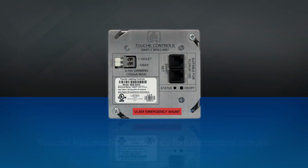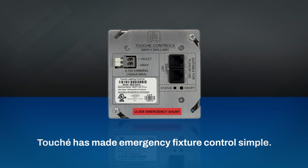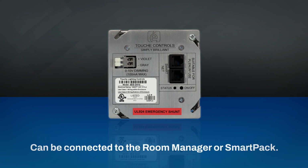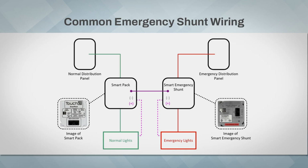As Touche does with everything, we came up with a simpler way to control emergency fixtures. We designed our own UL 924 listed smart emergency shunt modules. There are 2 different variations, one that has dimming and one that is switching only. The smart emergency shunt modules can be connected to the room manager or the smart pack and greatly simplify the installation.